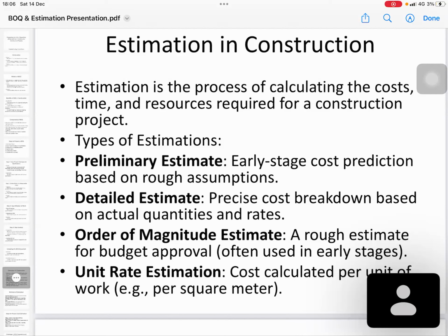And we are saying normally, if you are going for semi-luxury, 15,000 rupees per square foot. So very preliminary, no detail. Likewise, you have to have an early figure before you enter the project. Then you come to the detailed estimate.